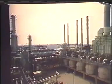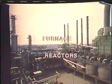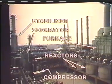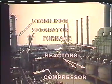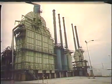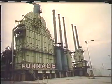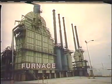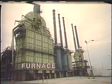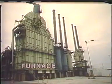The equipment in a typical reformer consists of 3 or more reactors, a furnace, a separator, a stabilizer, and a recycle compressor. The first step in reforming is to mix the feed with a hydrogen-rich gas, and then heat this mixture in a furnace to around 900 to 950 degrees Fahrenheit. This temperature is sufficient to totally vaporize the feed and allows the desired reactions to take place.